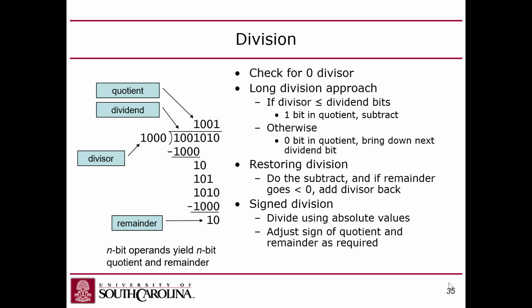If it's not negative, you just leave it the way it is. Then you shift the value over. So if I started out with this being 96, then I would keep shifting this value down and attempting to subtract it from the current value in the dividend register. You guys with me? Does that make sense?